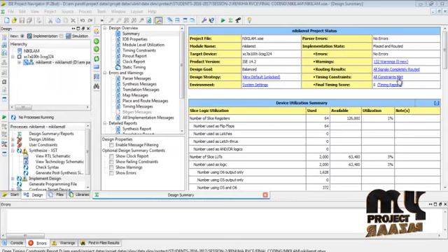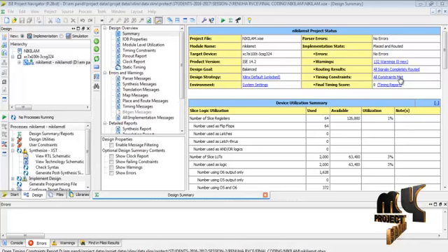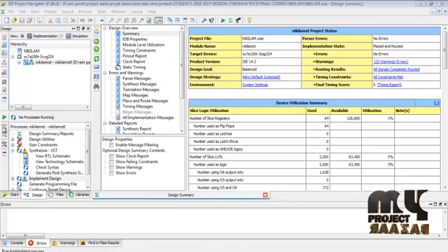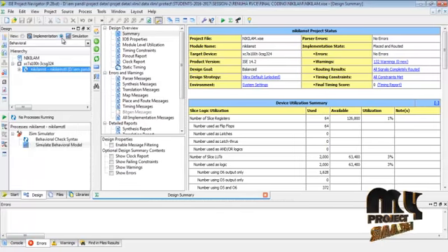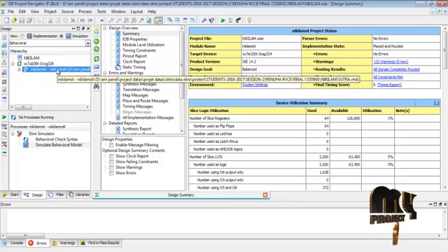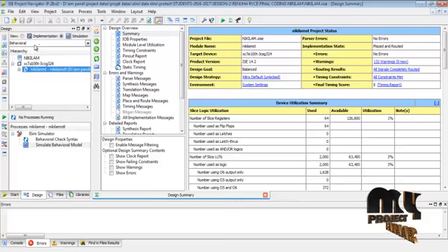Next we see the running process of our product. This proposed implementation is done in the Xilinx software. First open the Xilinx software and create a new file. After creating the new project file, we assign which kind of coding we are going to develop. Here the proposed implementation is VHDL based coding, so we click the VHDL module. After that, two kinds of output can be shown. The first one is the simulation. In simulation, we select the main file, then run the behavioral model, and the corresponding output will be shown.